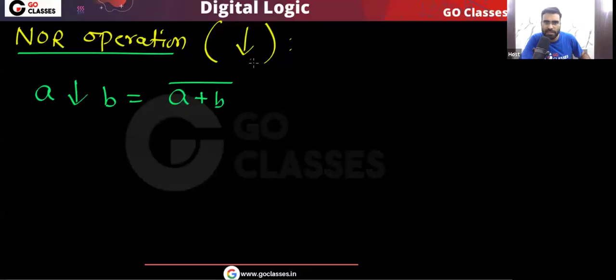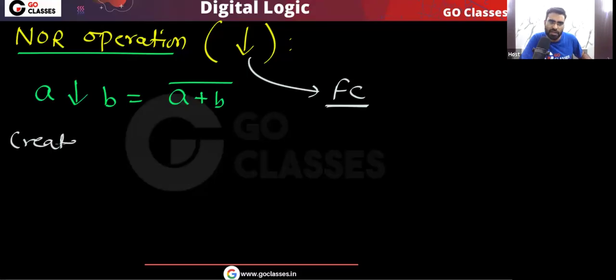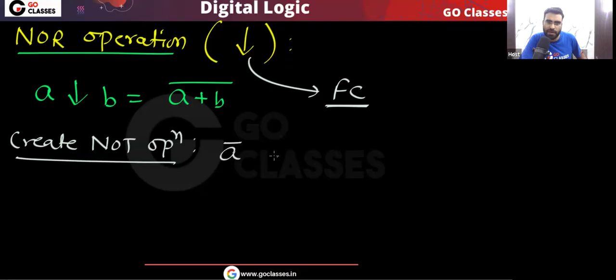Now, I am saying that this NOR operation is functionally complete. What it means? This single operation is enough to write any Boolean function, to express any Boolean function. Only this NOR operation is enough. With help of NOR operation, we can write expression of any Boolean function. Okay, so can you create not operation? Tell me. Can you create not operation? For example, this A bar. Can you create this A bar with help of NOR? Yes, of course. Very simple. A NOR A. That will give you A bar.